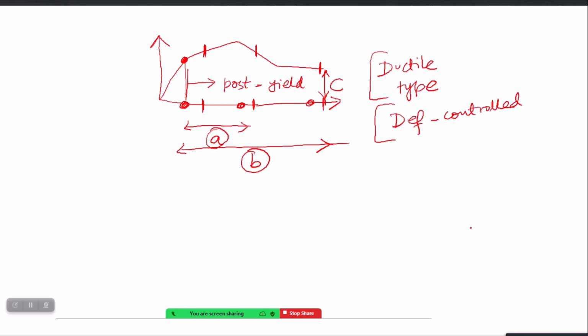But one thing I should explain here: these are all modeling assumptions. They should be in complete conjunction or agreement with the actual situation of your beam also. For example, if you assume that these two ends of this particular beam have a ductile plastic hinge, it by default means that your actual beam also will be having a ductile detailing at these two ends also.